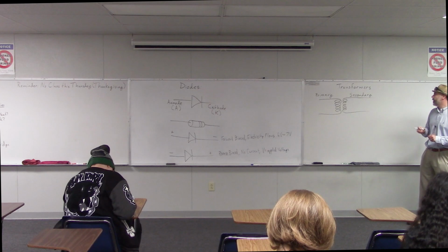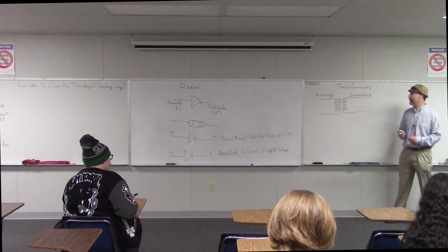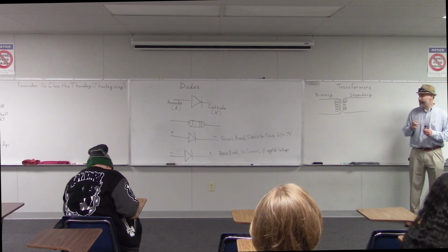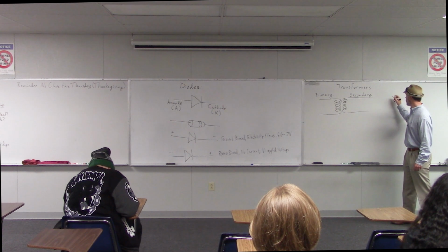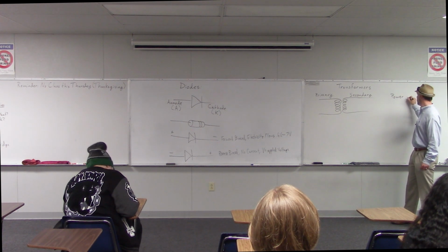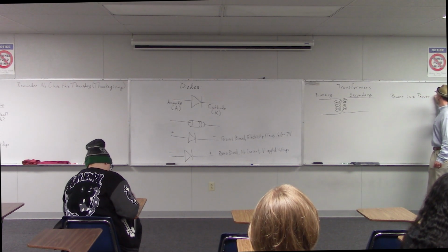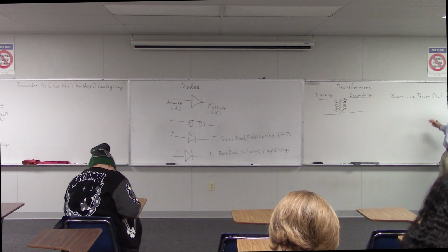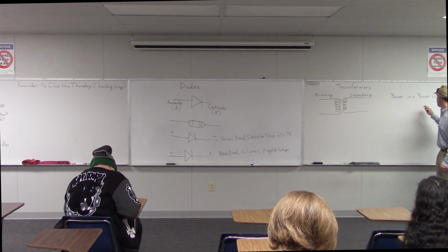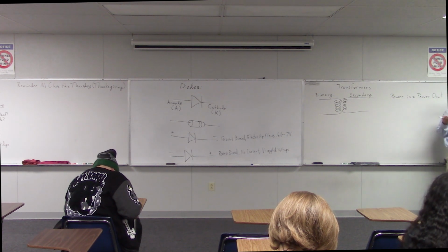Now, what about the power? Does the power change between the input and the output on a transformer? No, exactly. So for transformers, the power in equals the power out. And remember, power is voltage times current. So what that means is that on the output, if the voltage goes up, what happens to the current?